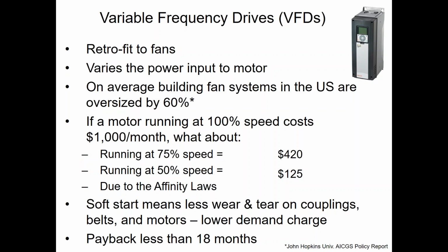See, Scott has a question. Scott actually has a building where the fans were undersized and they ran the VFDs above 60 hertz. And he's asking if that was bad for the VFD or the fan. I would suspect it probably wasn't good. I don't have any data to support that, and I've never seen anybody run the fan over 60 hertz. But unless the system was designed for that, it might be challenging.